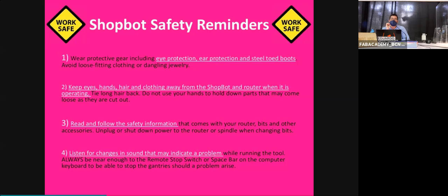So always safety glasses. Always use ear protection. When we cut, we are usually producing a loud noise, around 80 to 90 or 100 decibels. To give you an idea, with 90 decibels for more than 3 minutes, you start losing hearing. So if you want to lose your hearing completely, it's up to you. But if you don't, use ear protection.